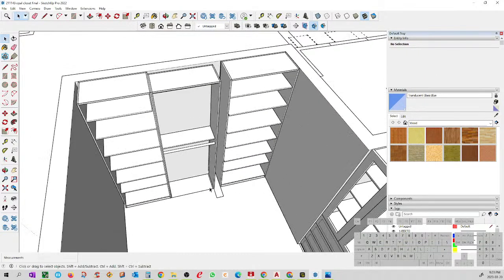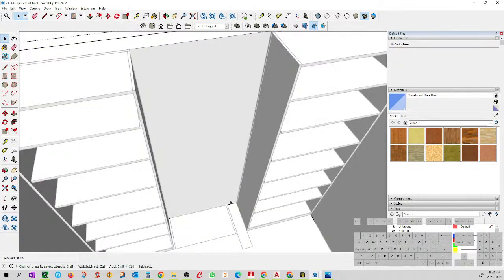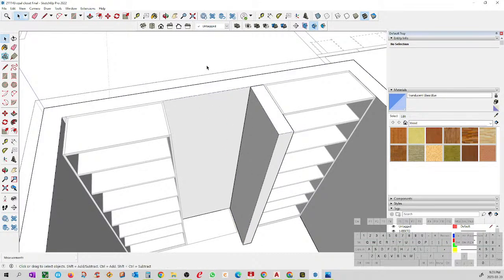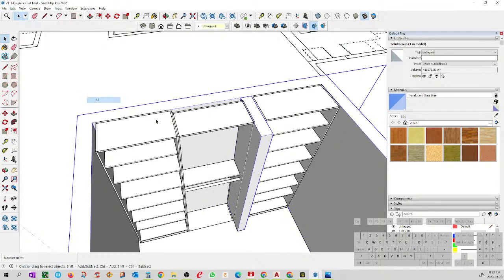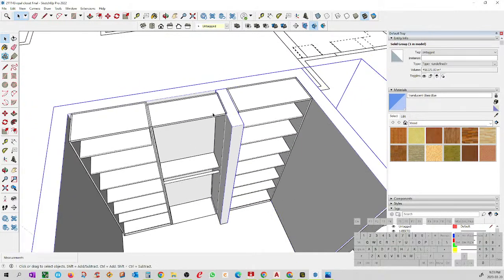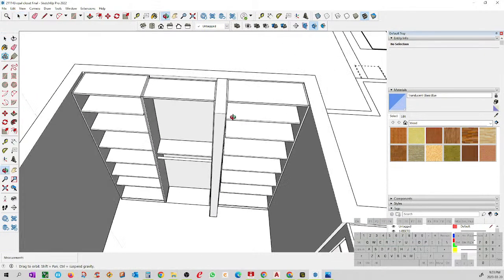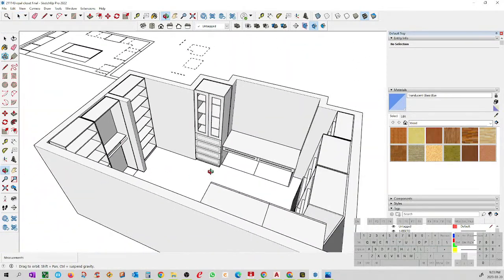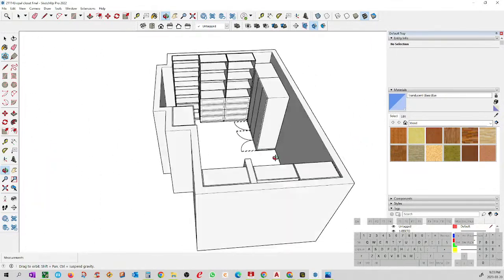This is also a wall, so I can hide this and create this wall. Double click, create another wall here, and escape. So now this is part of that, and just go edit, unhide all, and that gives us, okay. So there you go. So now that's a full closet, very understandable, very clear. You can see and have a visual of what's going on.